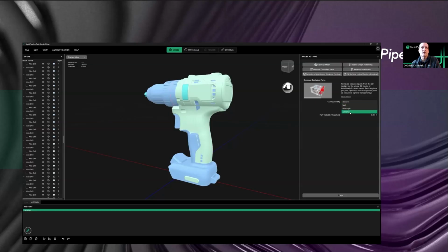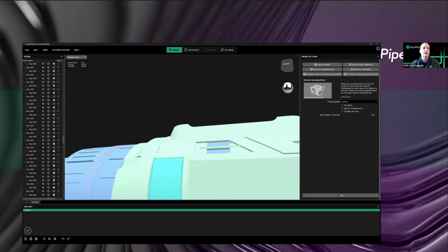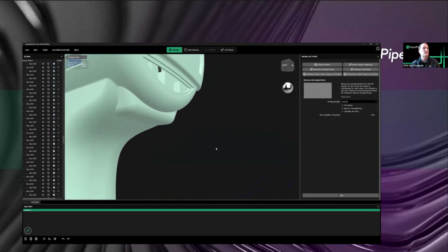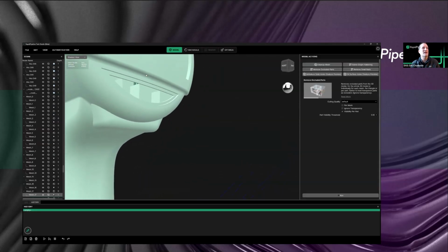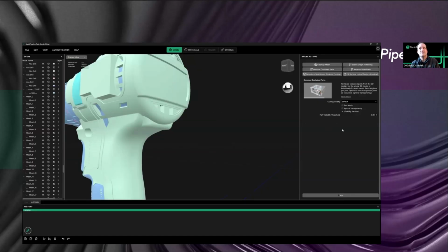There's fast, thorough, or extreme for how many rays to shoot at the object to figure out which rays can see through. So for example, in this CAD asset, there's probably some gaps here that you can see through the meshes to see what's inside. So there we can see there's a gap there, and I can see some of the mesh inside. This controls how many rays are shot from the outside of the model to try to find interior models. And if it can't find it from enough rays, then it'll say, oh, it's cullable.